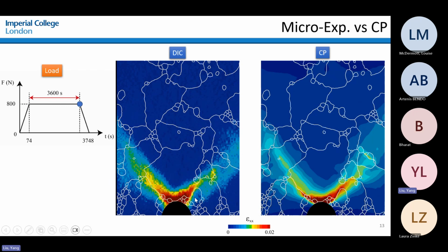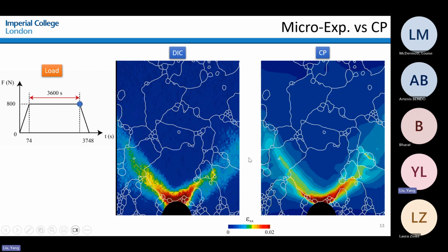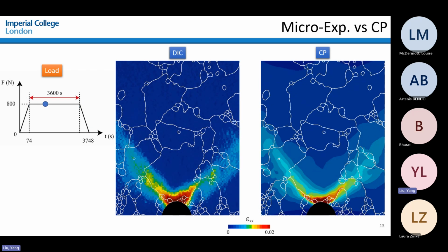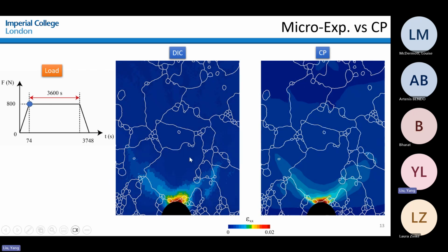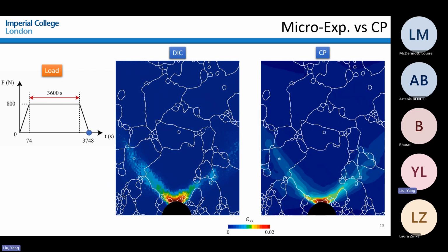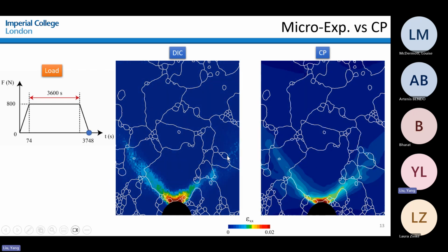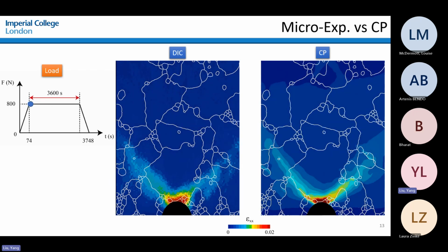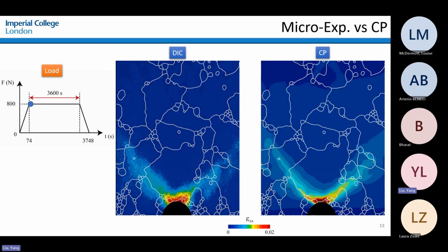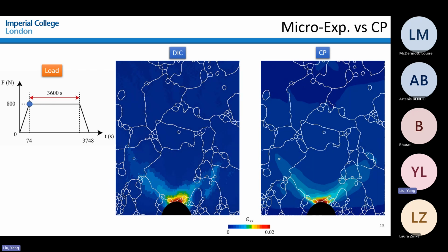And the creep strain accumulation is massive compared to the other deformation mechanisms, where basically in the bulk, it has been reported that the plastic strain accumulation and also the rate sensitivity of the material is minimum. But actually, in the real sense, near the notch, we have rate sensitivity which is significantly higher than the bulk material. So there is heterogeneity of the rate sensitivity at the crystal level.